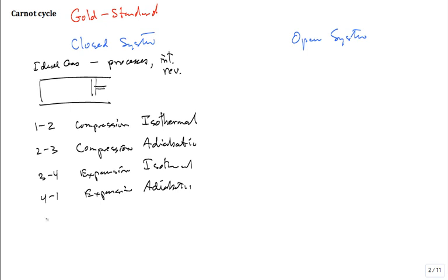Right? So we can explain this on maybe a temperature entropy diagram. Well, and you can also put it on a pressure volume diagram. But which one do you want to see first? Pressure volume or temperature entropy? Temperature entropy. Okay. So let's do this. If I have compression and it's isothermal, what does it look like on a temperature entropy diagram? Horizontal. It looks horizontal. It's isothermal, constant temperature. And it's going to be going this way.